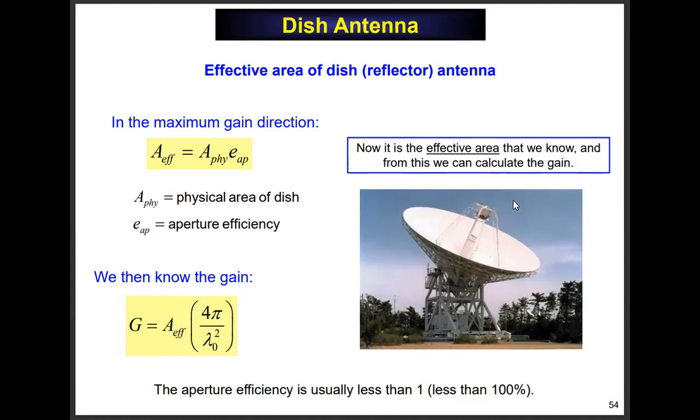It's the area of this big circular aperture. It's going to collect all the energy that hits it, right? So I already know the area. So now you can go the other way and use it to calculate the gain. Now, there's one caveat, okay? You might think that the effective area is just the physical area of this big circle, and that's not too far from being true, but people like to sneak in something that they call the aperture efficiency.